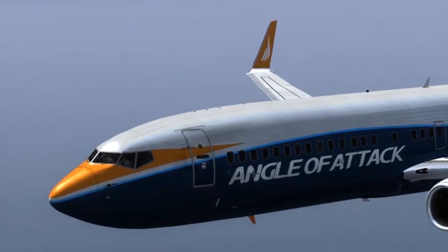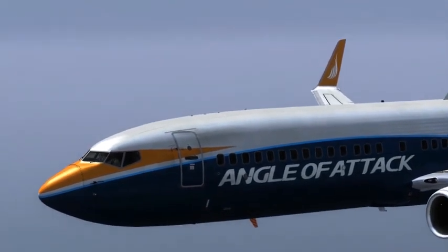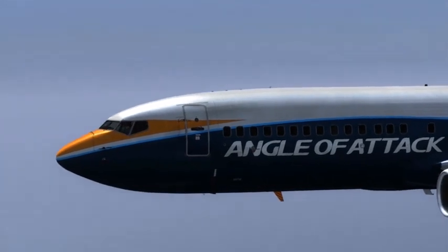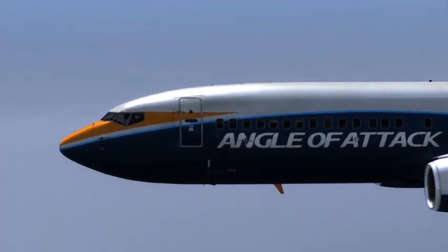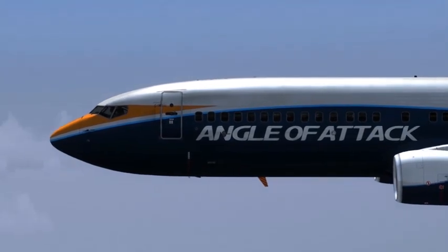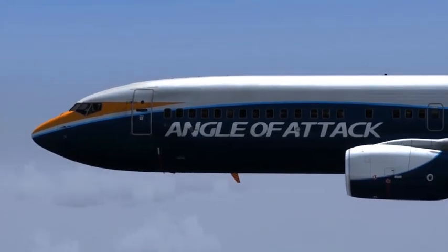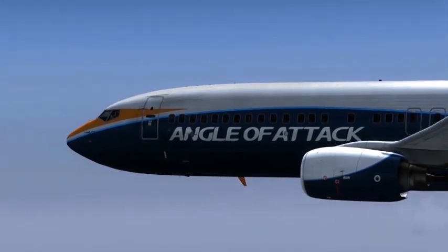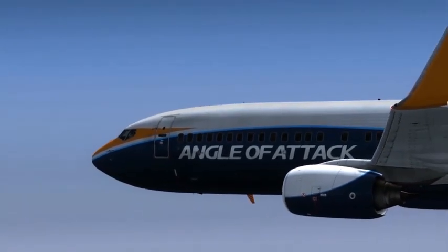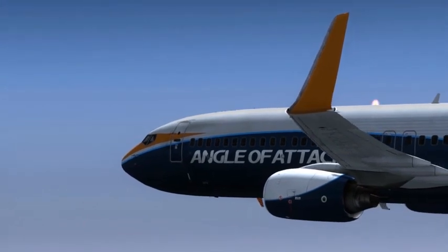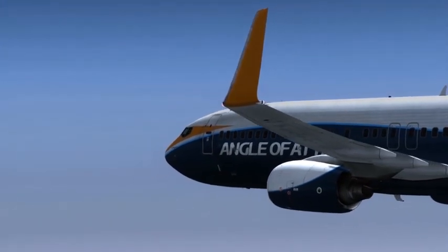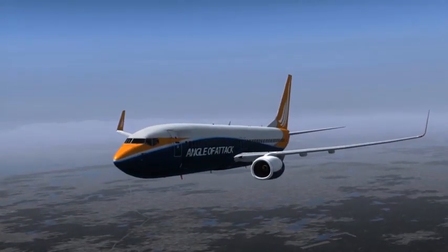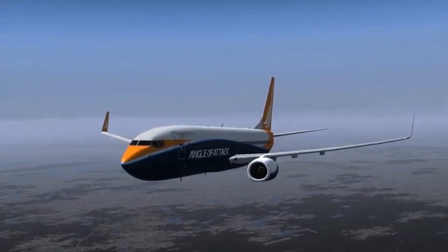However, when the intended landing field elevation is higher than 8,000 feet, there are different sets of rules for pressurization. If the landing field elevation is greater than 8,000 feet and the flight is less than 60 minutes, the cabin altitude during cruise will be equal to the landing field elevation. If the landing field elevation is greater than 8,000 feet and the flight is longer than 60 minutes, the cabin altitude during cruise is maintained according to the cruise pressurization schedule.